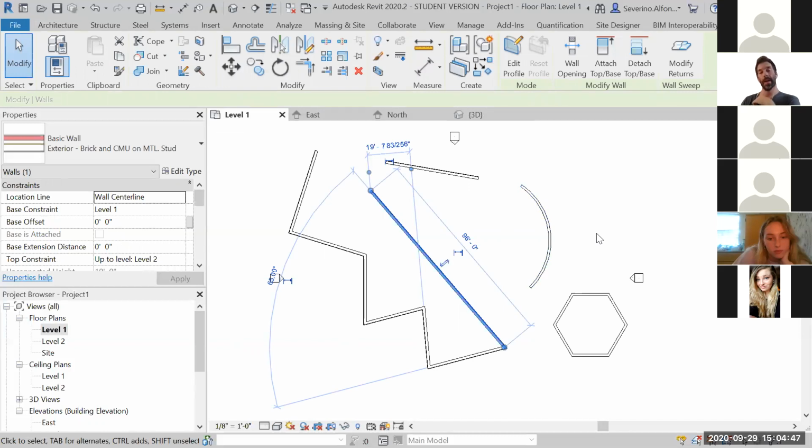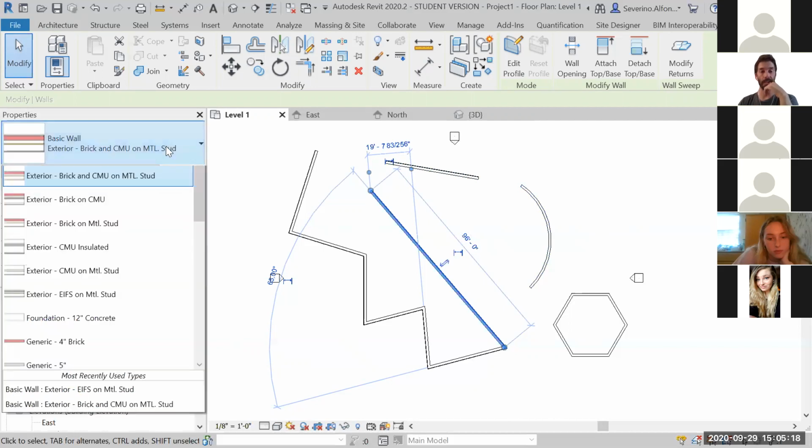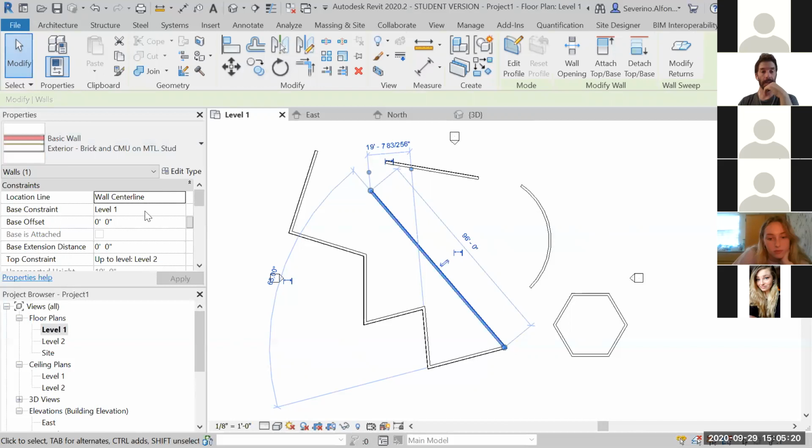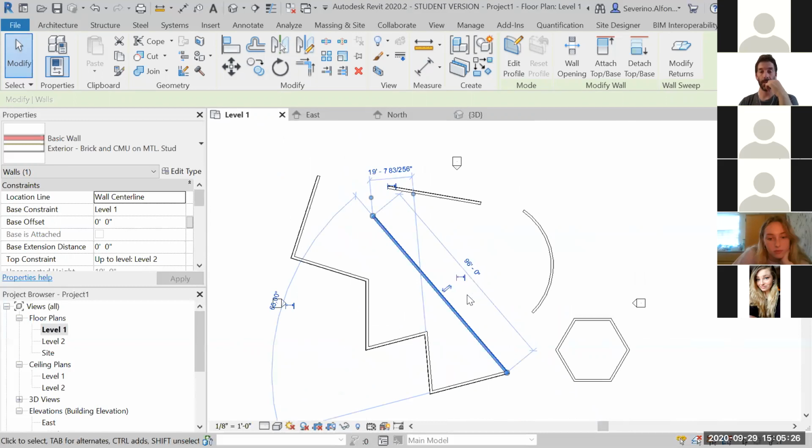Another thing that's a little annoying in the beginning, but later on is very much welcome, is that whatever you select in Revit, it gives you all of these parameters and all of this information. Sometimes you might think, what the hell, I don't want all this, and I can't see through it. Well, that's an issue of accommodating the eye and the mind to say, well, some of this stuff is actually useful. When you select something, you not only get the properties, which means I can change the properties and the heights and everything, but I can also see that wall is exactly 96 feet long.